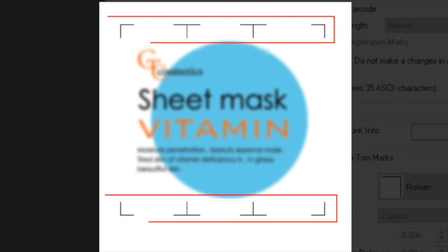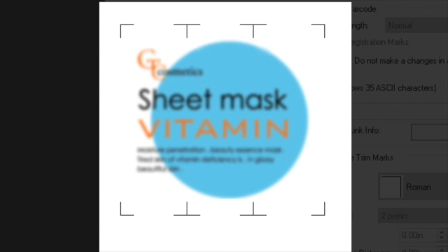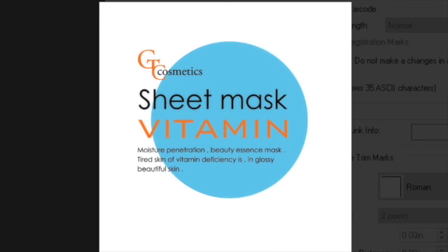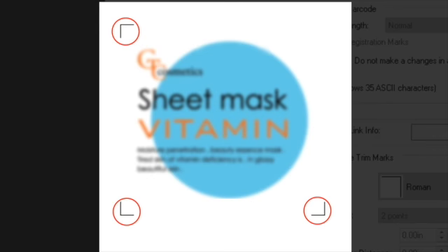Segmented registration marks are primarily used for longer cut jobs ranging from 3 to 50 feet, and determine if any bowing occurred in the printing process. Segmented patterns can be used with any print and cut job for the FCX 2000, but won't usually be necessary. The remaining choices determine the number of registration marks used, such as 3 points and 2 points.